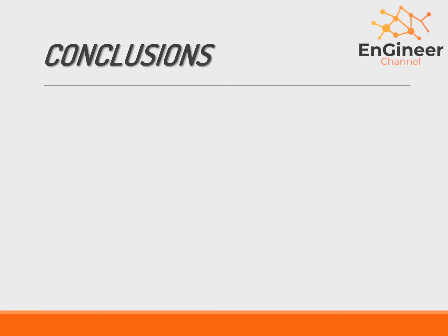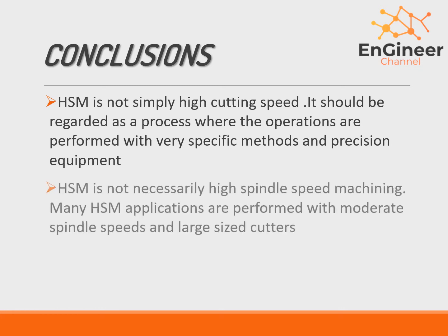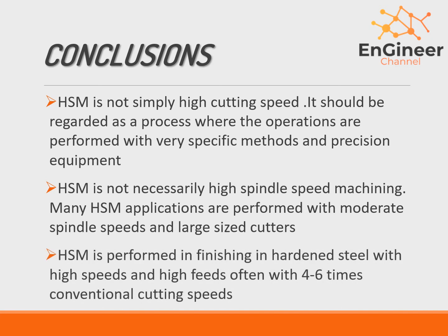Seeing now conclusions. HSM is not simply high cutting speed. It should be regarded as a process where the operations are performed with very specific methods and precision equipment. HSM is not necessarily high-speed spindle machining. Many HSM applications are performed with moderate spindle speeds and large-sized cutters.